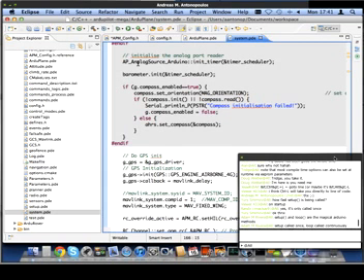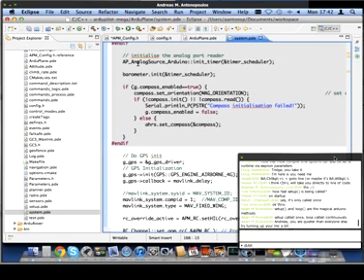So after we've initialized the ADC, just a quick point here. As you can see on Eclipse, one of the useful functions it offers is that when something is not defined, it grays out that piece of code. The reason this is gray is because this type of compass initialization is not used in my particular configuration. So that way you can see how the hash define enables or disables bits of code visually.